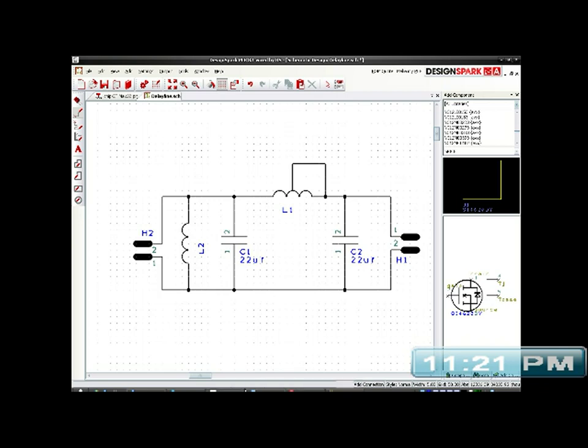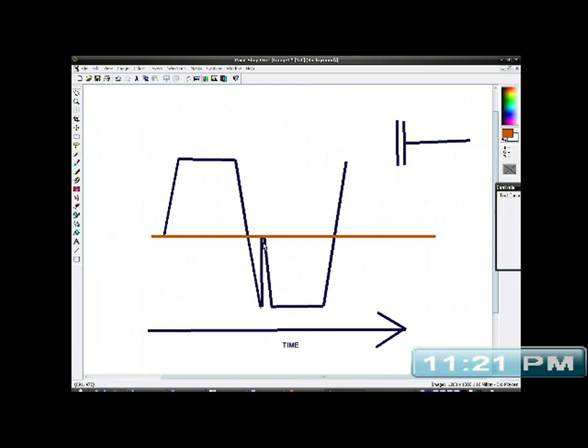So this pulse here would be about half its way up if it has a larger capacitor, but it'd be a bit wider. Well, I want the pulse to be coming up to 0 volts, or basically in the center. So using a larger capacitor doesn't help very much. But if I use a smaller capacitor, I get a bigger spike, but it's over a shorter period, over a few microseconds, right?